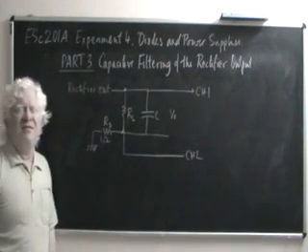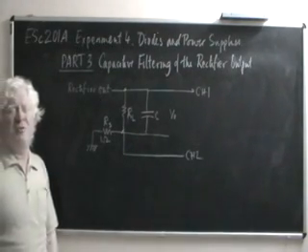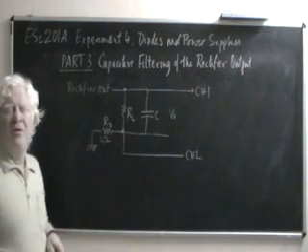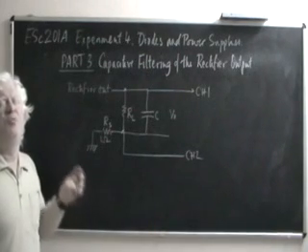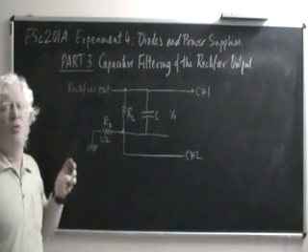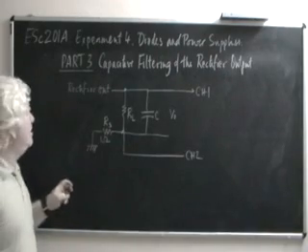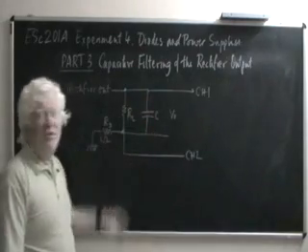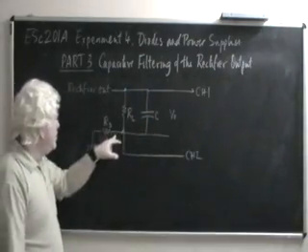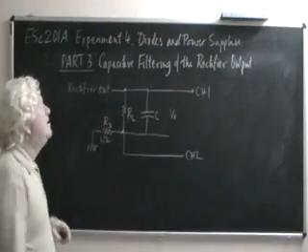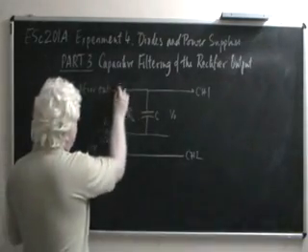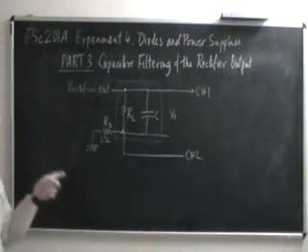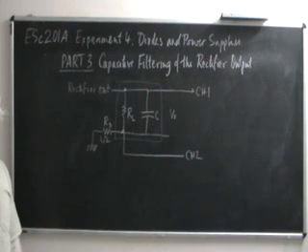The series resistance is required to make current measurements. It is very interesting, and we will come to this in a moment, that the current flows for a very small, minuscule portion of the cycle. And the current doesn't just flow through the resistor, it flows through the capacitor as well. So the current that actually flows through Rs is the net current taken by this entire portion of the circuit. And that is what will be of interest to us to understand.